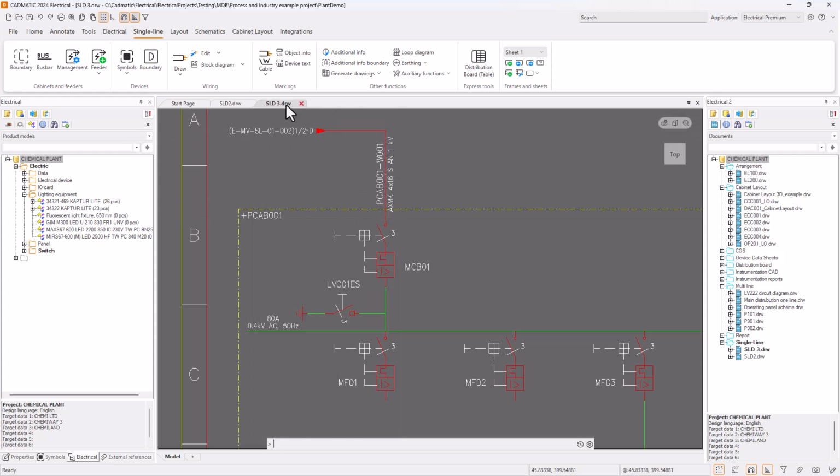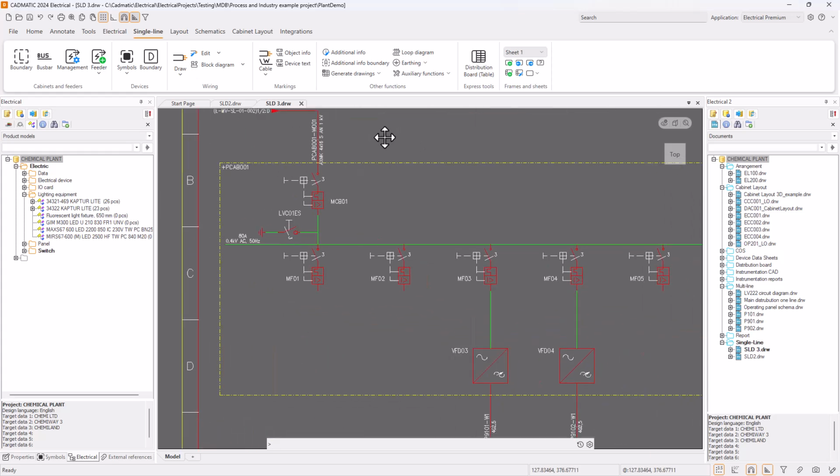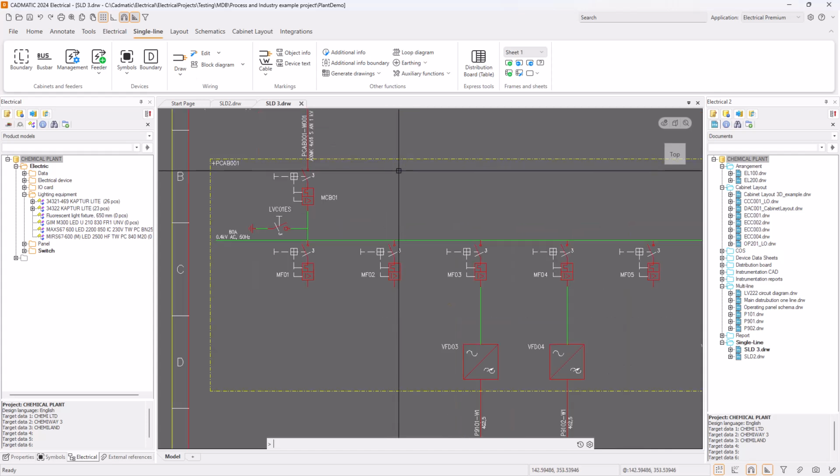So even if it goes to another file, we can work with these and use those wiring reference features in electrical to find out the head or tail location of this cable in this project. So it's not needed to use only one file. You can have several files in a project, and links between the files can also be created because of the project database. That is maybe one of the most important things in electrical premium level that we can achieve with the project database.